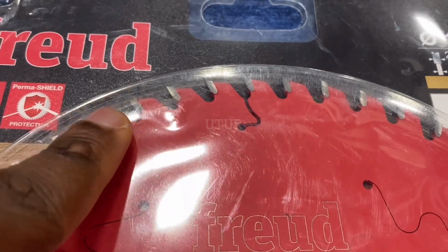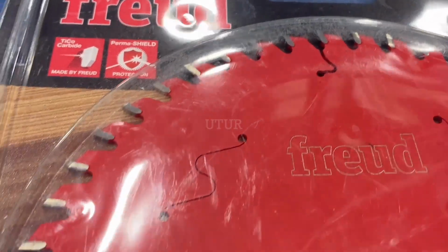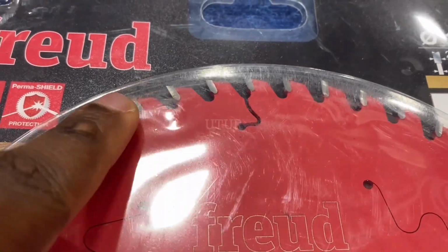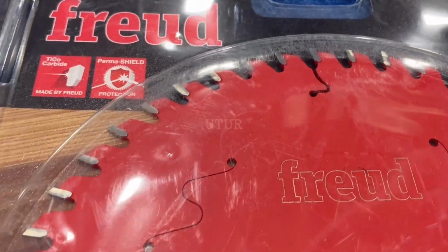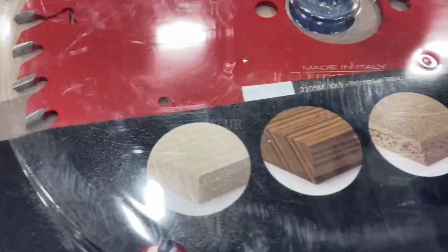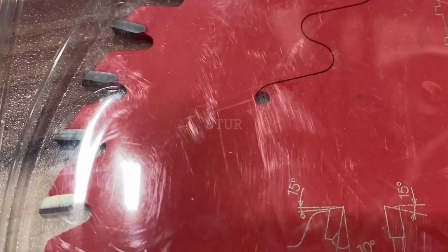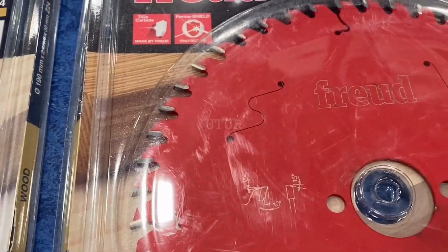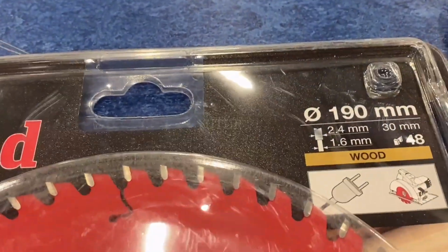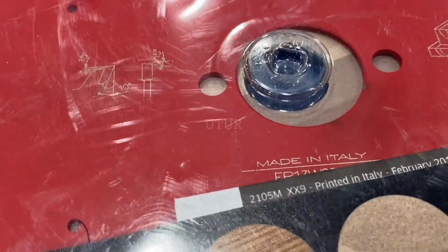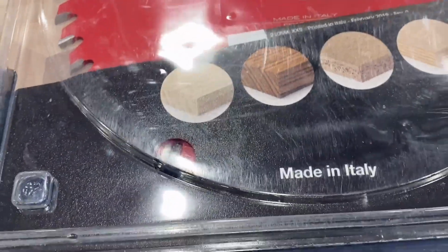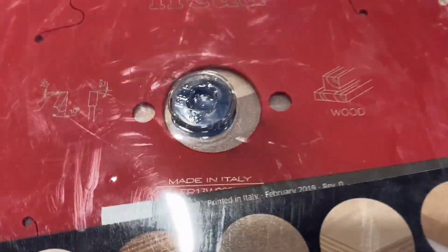And so, if the bevel of this blade is 15 degrees, I would be inclined to say that this is an all-purpose ripping and cross-cutting blade, okay? Which can be used for medium ripping and cross-cutting. That's because an optimum ripping blade has got about 24 teeth, whilst a cross-cutting blade is anywhere between 60 to 80 teeth. This quality blade has got 48 teeth, which means that it does a moderately good job of cross-cutting and ripping, but not optimally, okay? It's not a designated blade, but rather a general purpose blade with small gullets.